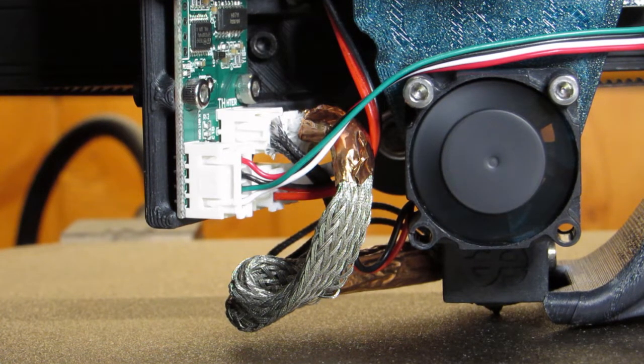So you're hearing it, you'll hear it buzz. Now you know it's touching. If you just lift it above that so the buzzing stops, or you leave it just where the buzzing starts, you're as close as you're going to get manually to Z actually equals 0.